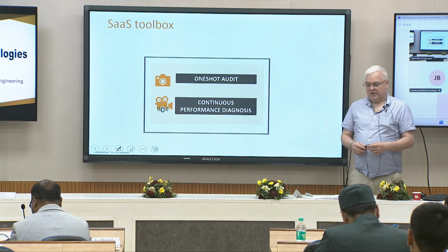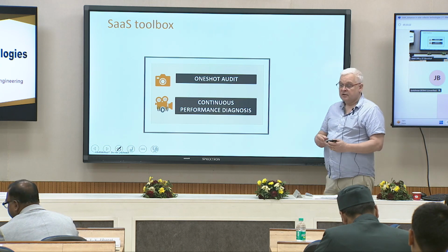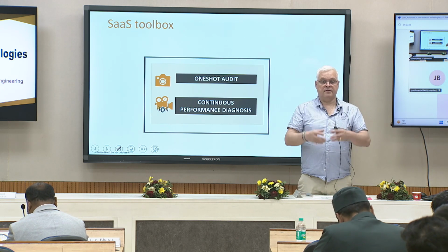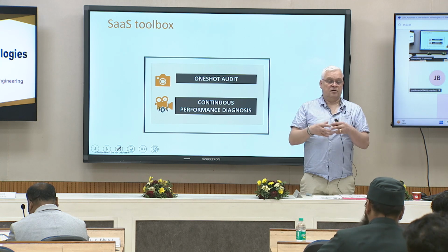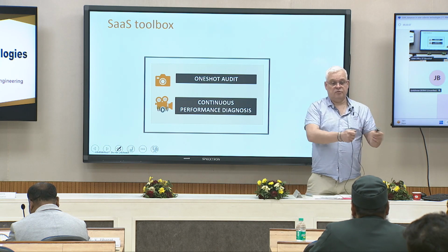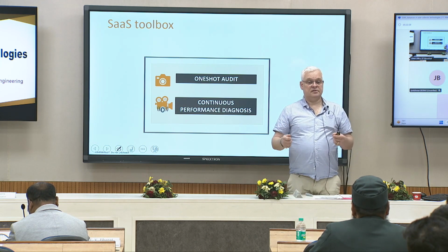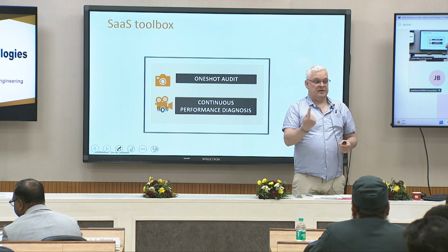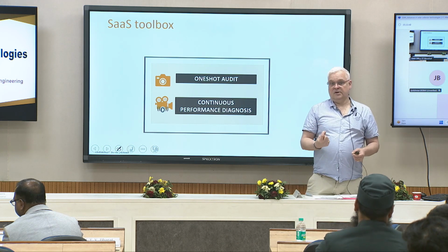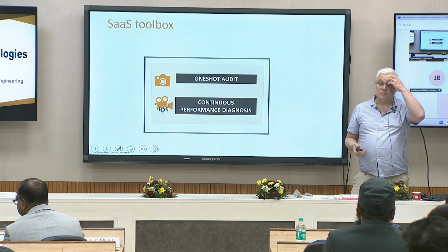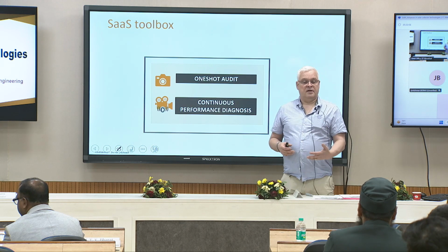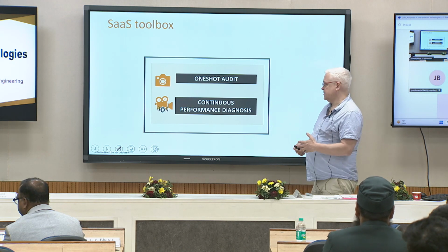and the building. Another problem that could be a small self-shadow. That means that you have on your roof a chimney, okay, or a ventilation system, and the installer put PV panels around this. That means that during the day it will generate shadow all day long. A small shadow, but a shadow. It happens also to have such problems, which means that since the beginning the PV installation has not been well integrated. Okay, so the audit is necessary.